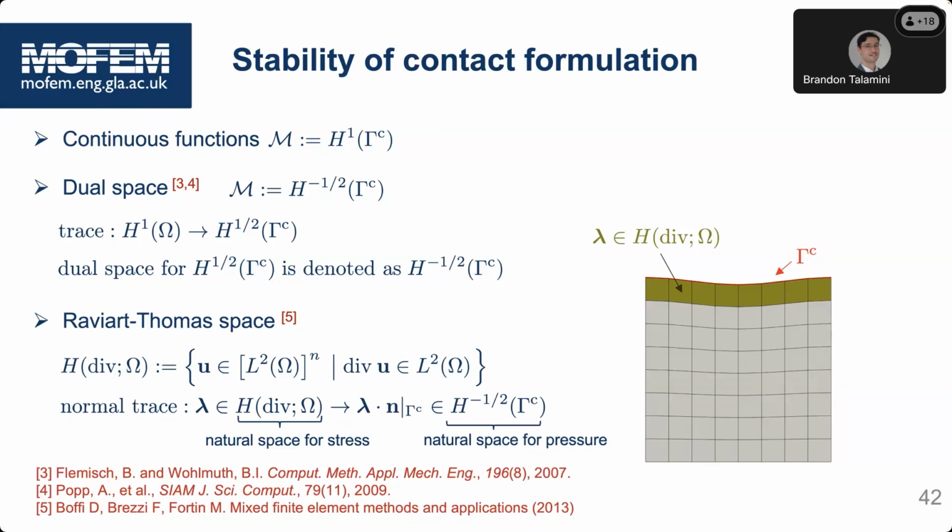Yeah, exactly. Elements that you represent, and so then you have to exponentiate them to get the actual full rotation and the right Cauchy-Green, the U tensor. Okay, so all right. But the rotations are easy because you have a Rodrigues formula. Yeah, it's closed form, and we do that as well.